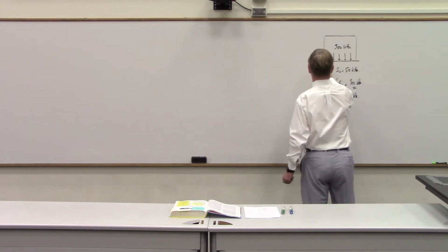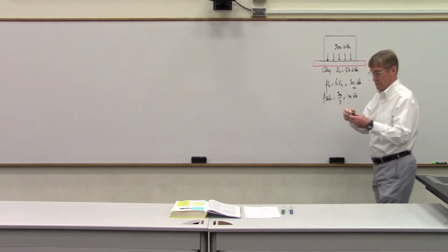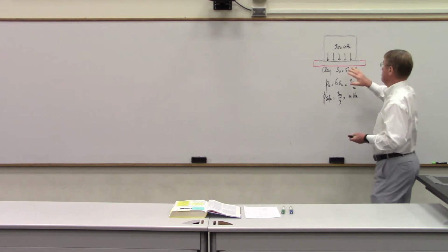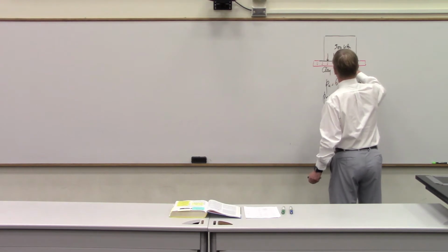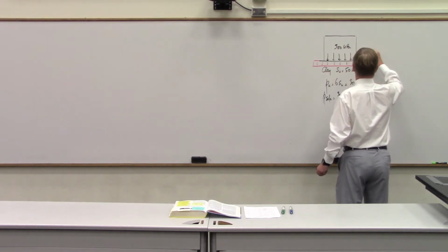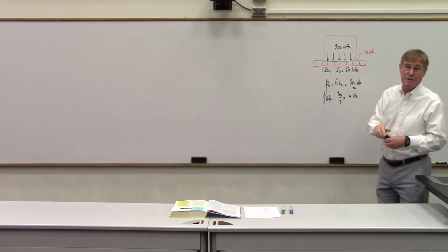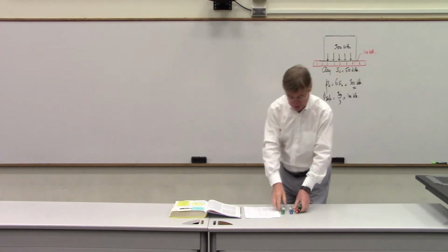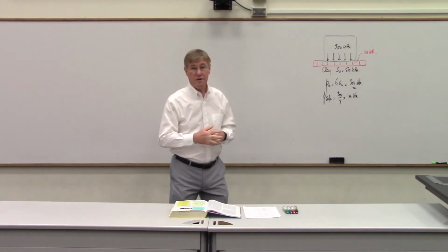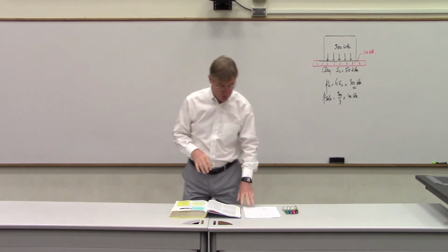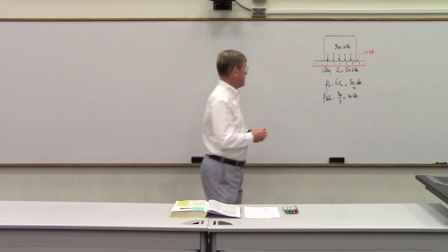And so we would calculate the width and the length necessary for the foundation to generate only a safe pressure. So it's likely that the foundation would have to be larger than the silo itself to be able to reduce the pressure to something that would be much more manageable, say 100 kPa. This is a very simplified version of the process, but this is the kind of work that geotechnical engineers do when it comes to foundations and determining how much pressure you can put on the soil. Okay, so that was the Transcona Silo case history.